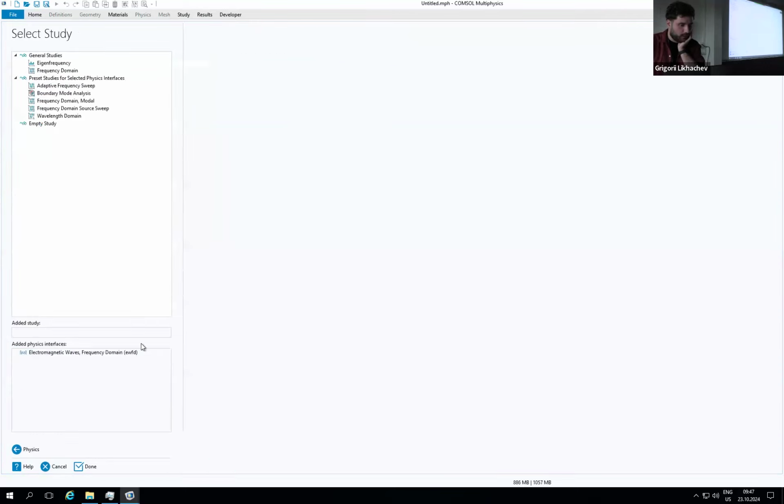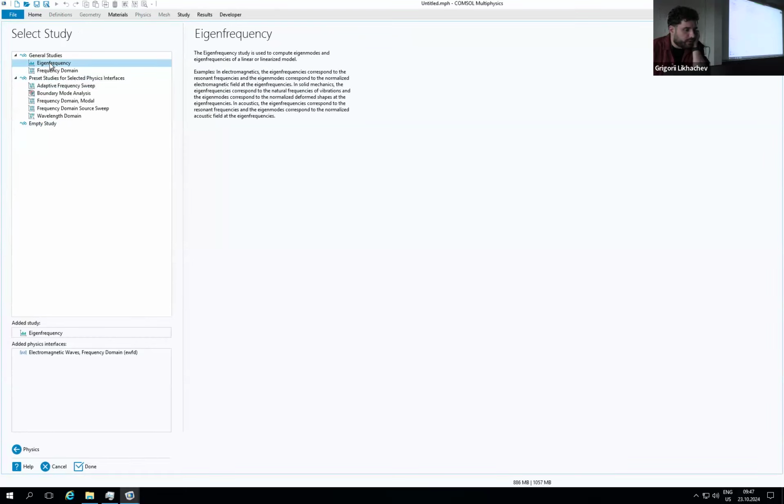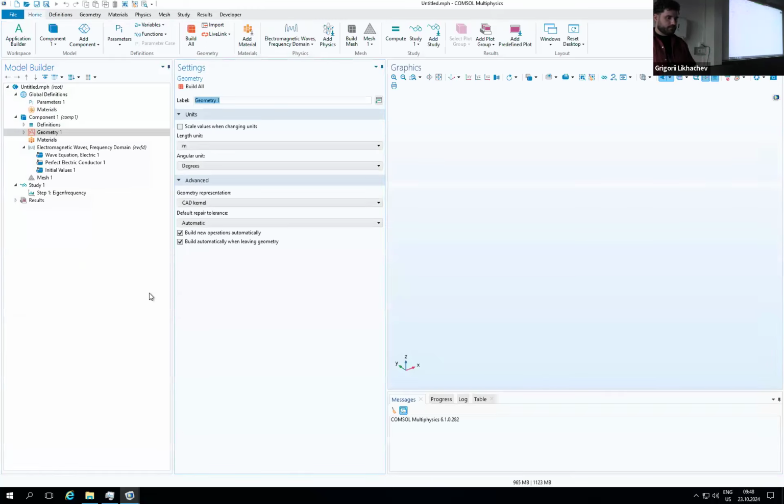Are we all here? All right, so we put it. We go to study, and what we put is this eigenfrequency. That basically will calculate the resonant frequencies of the structure that we give it. That's what we want. Are we all here?